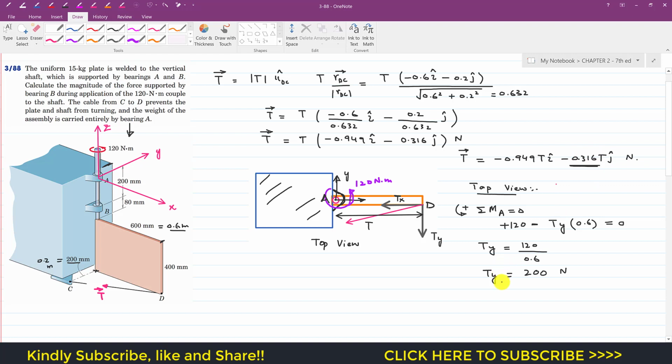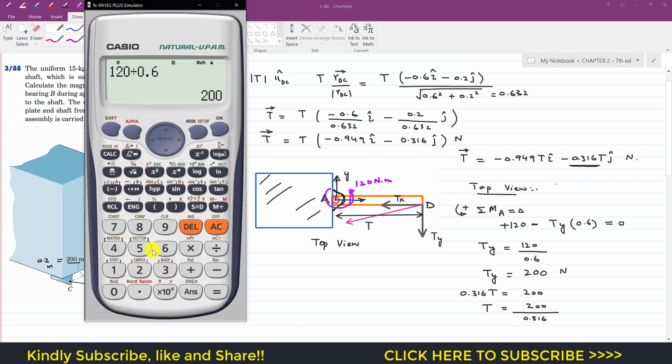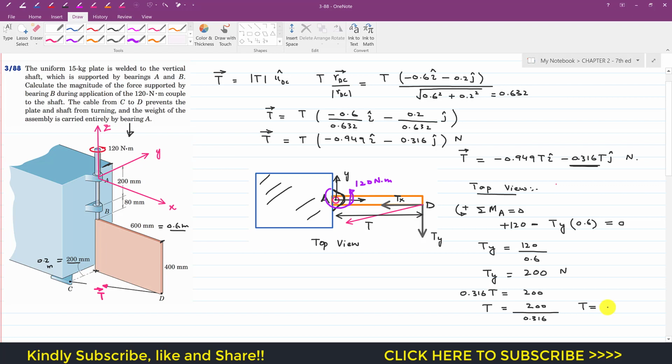And now from here we know that this is Ty, this is 0.316 T. This is only the magnitude, right? So we can write 0.316 T equals 200, and since we want to find the T magnitude, this will be equal to 200 divided by 0.316. This gives us 632.91, right? So this T is equal to 632.91 newtons.